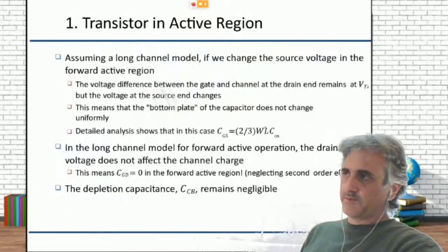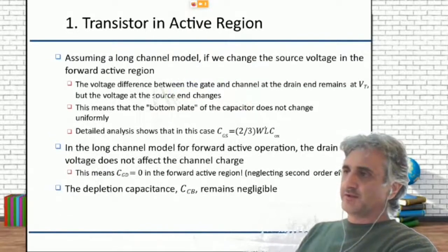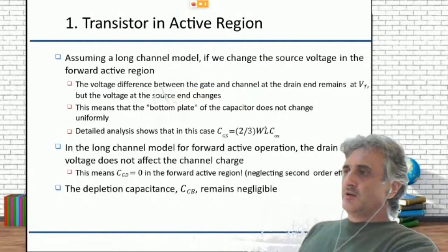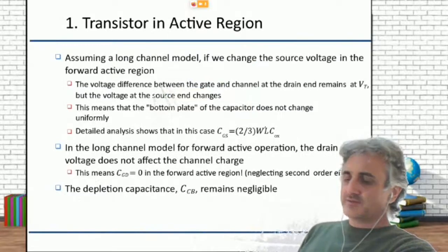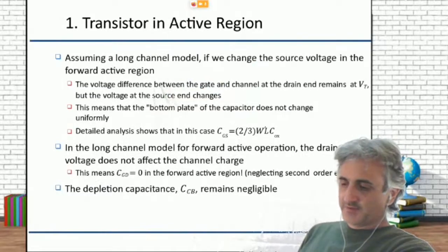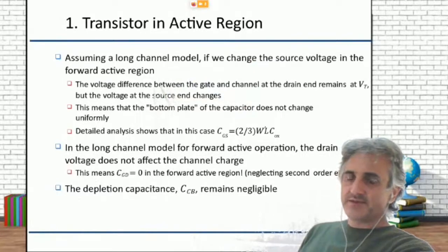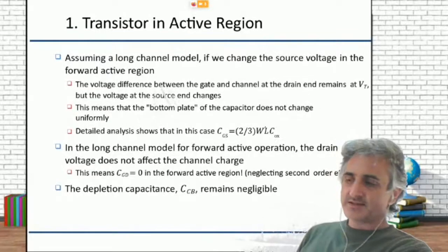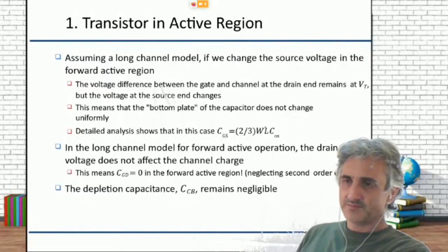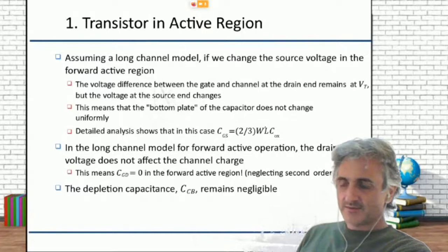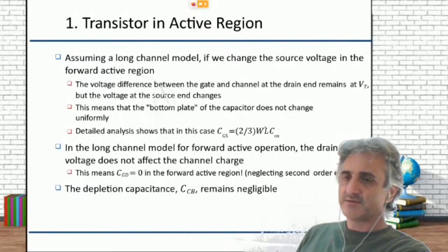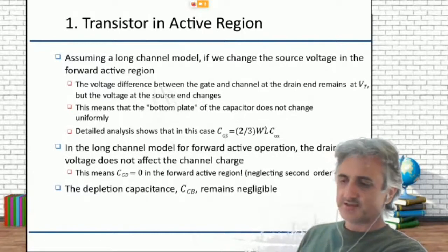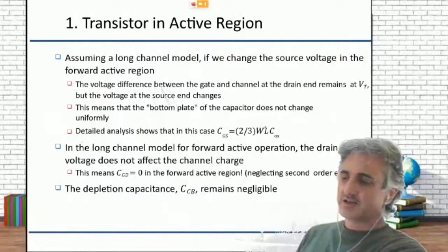No? Okay, now the active region. Notice that there is a very interesting thing, which is that changing the VDS, the drain voltage, the current will not change. Can you imagine that? You are changing the VDS and the current is not changing.